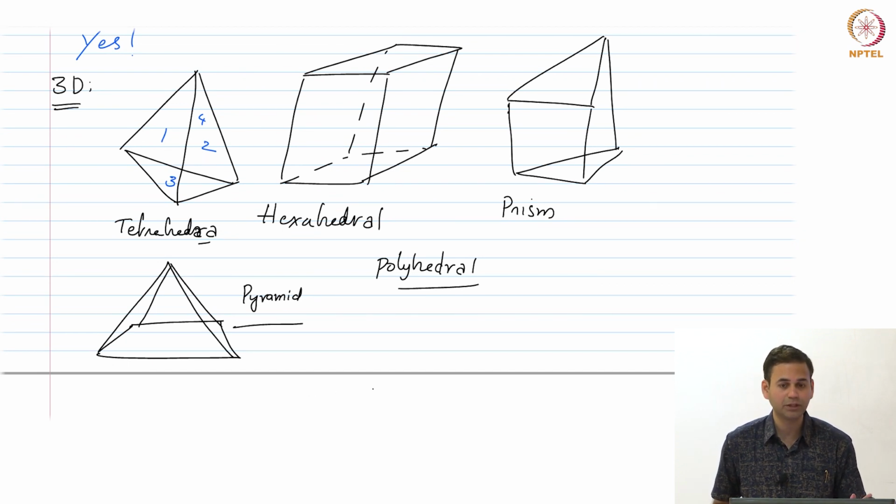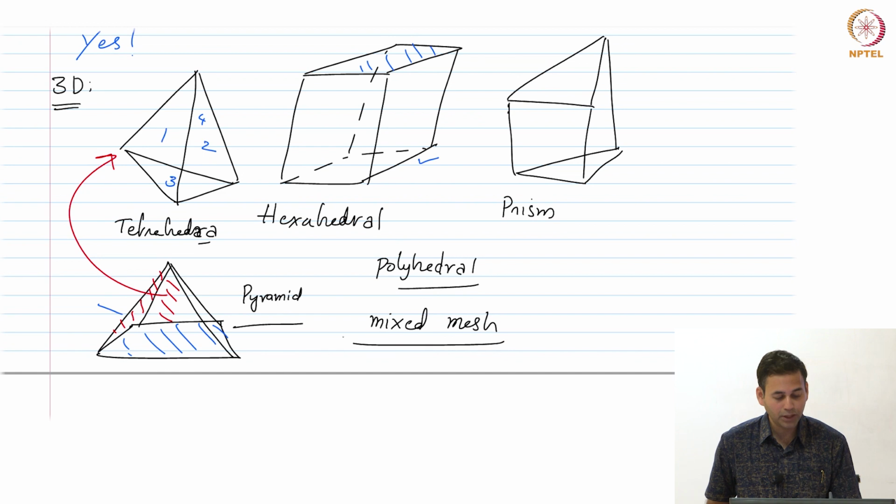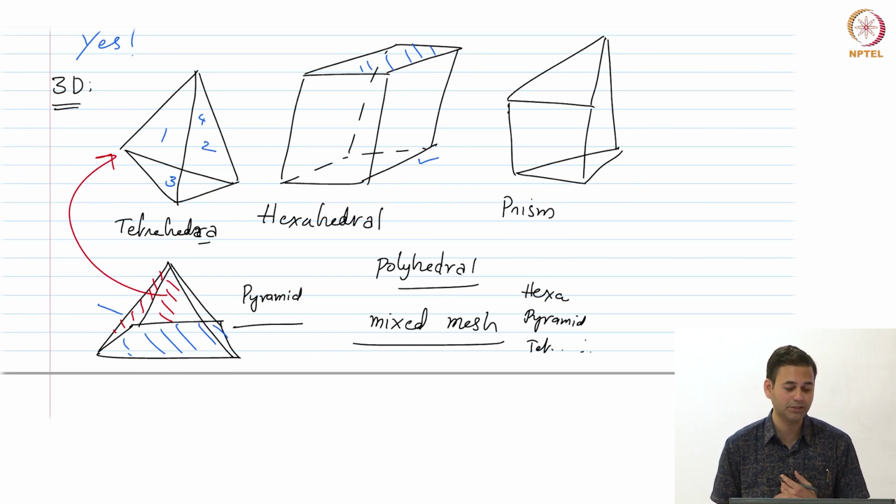Of course, all these mesh shapes remind us that we can also have a single mesh with different cell types, right. Close to the walls, we may start off with hexahedral cells, okay. And as we move away from the wall, we may put pyramids on top of these hexahedrals, by matching this face with these faces, right. We can have pyramids sitting on these hexahedrals. Once you have a layer of pyramids, the triangular faces that these pyramids have can be attached to tetrahedra, and build tetrahedra and so on, right. You can have a mesh like that, which is a kind of mixed mesh, where you can generate hexahedra, then a layer of pyramids followed by tetrahedra and so on. Of course, you can also involve prisms and things like that. So, these can also be built, depending on the application, okay. Fine. So, we can also have a mixed mesh, that is the takeaway.